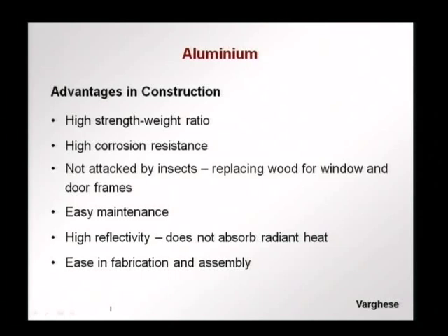Similarly, we find aluminum being used for framework of partitions where traditionally wood would have been used. It is easy to maintain. Generally, the anodizing or the powder coating lasts for a long time, and it need not be periodically painted or maintained in any other special way.